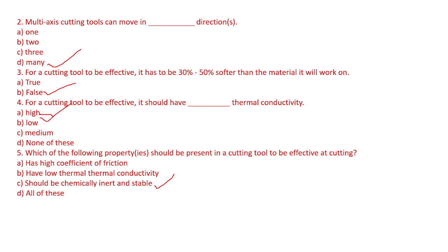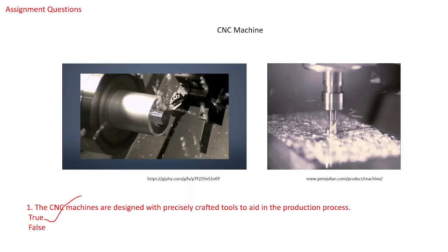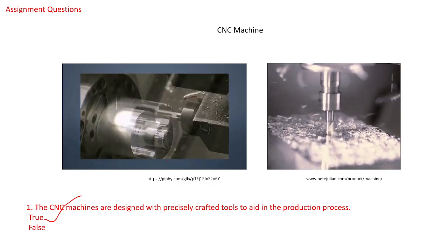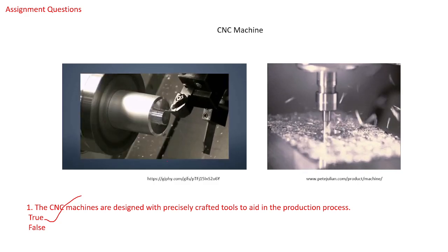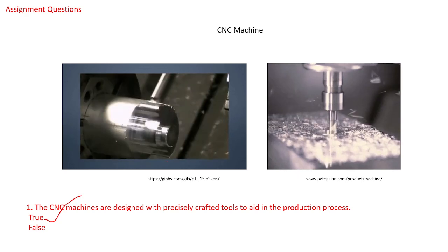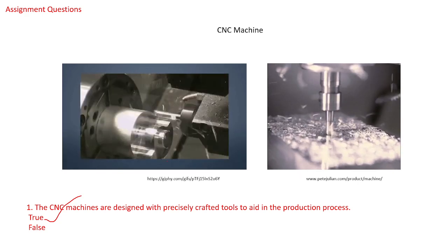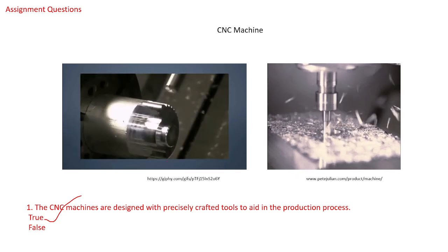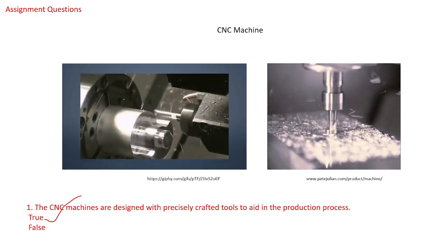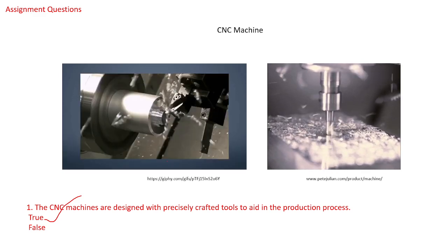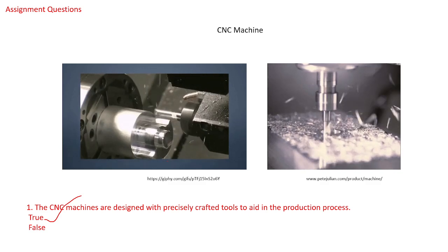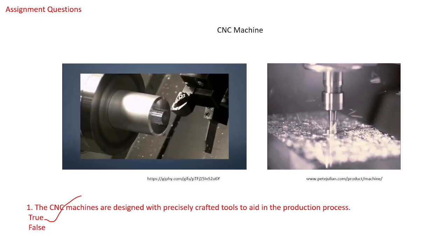Madam, while explaining milling and turning, showing that displays, you said it makes an accuracy of 1 micron. Generally, it's not possible. It will be around 10 microns. It's very difficult to achieve 1 micron. Generally, in a jig boring machine, we'll get around 5 microns.